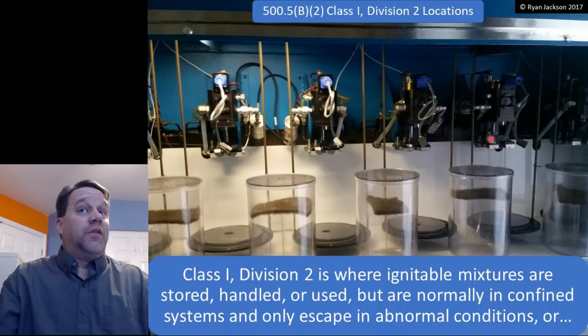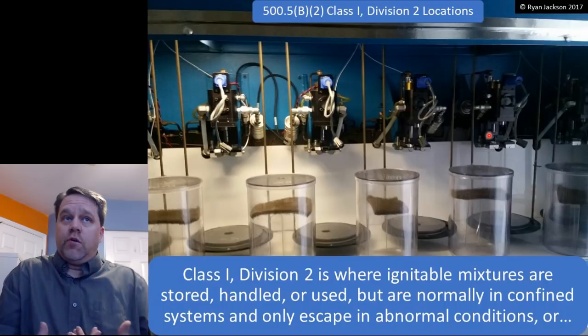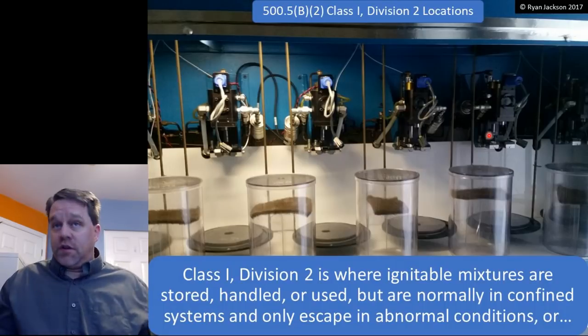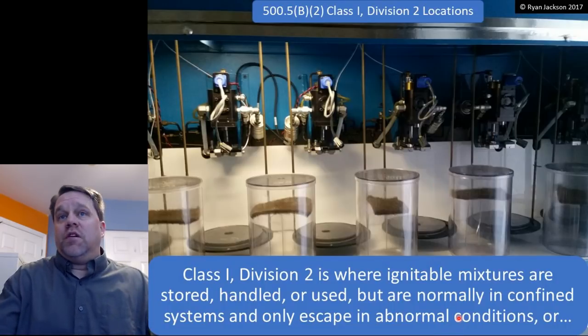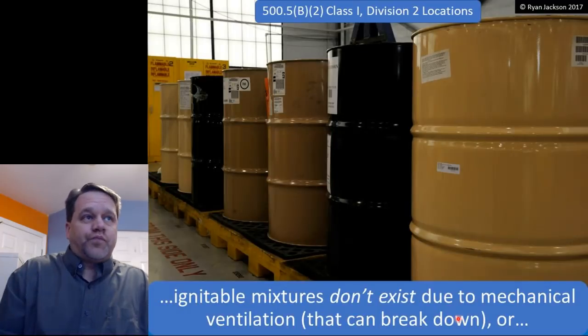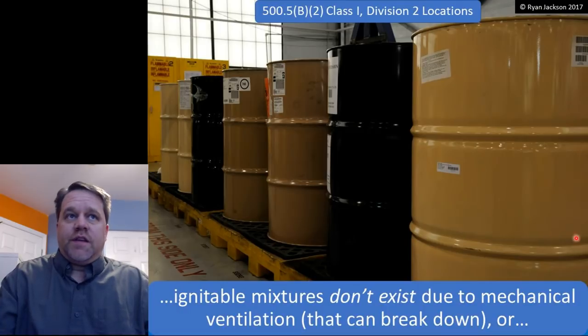If the plexiglass were to break, then sure, that gasoline vapor would go into the room and that would become an ignitable mixture. But that's not a normal occurrence. That is only under what? Abnormal conditions. So Class 1 Division 2 is when the ignitable mixture exists under abnormal conditions. Or where ignitable mixtures do not exist because of mechanical ventilation that can break down.